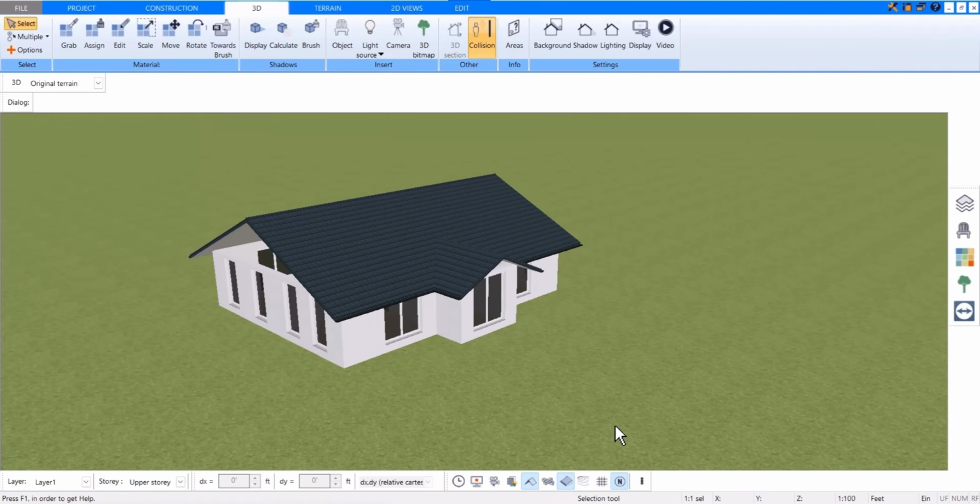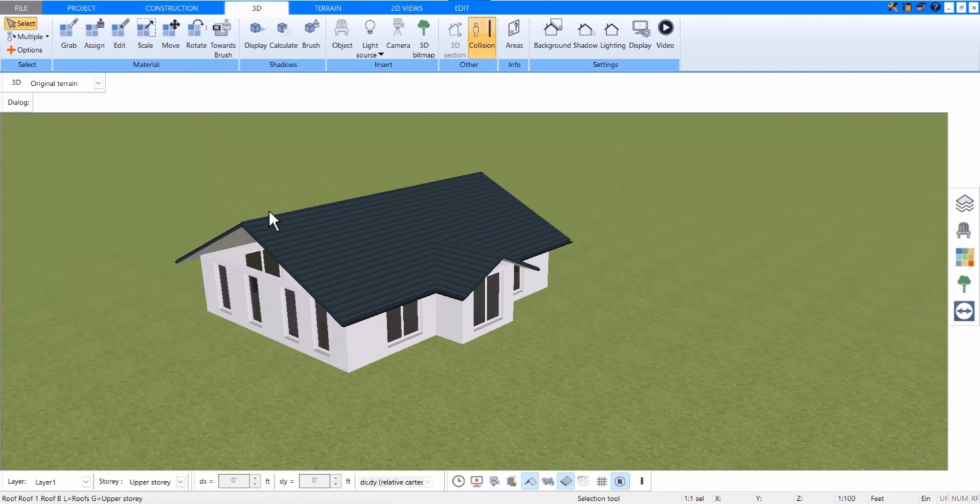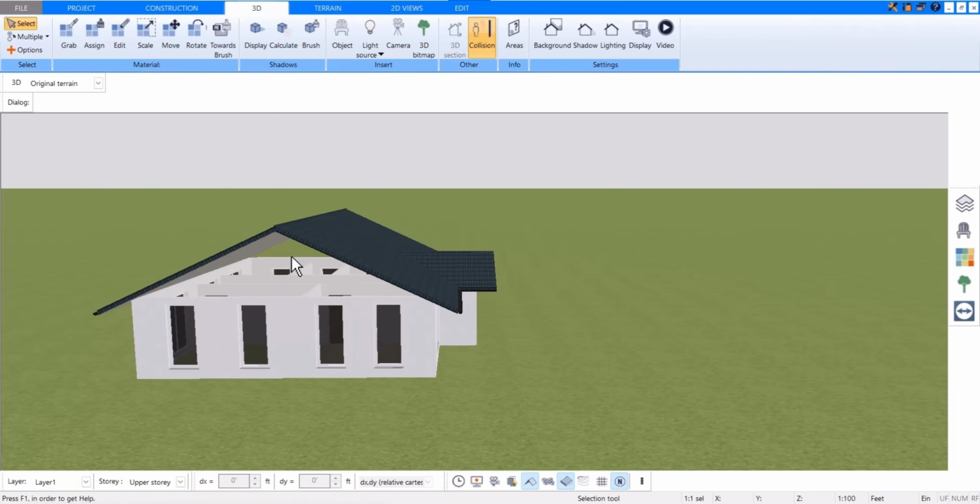For that, I go down to the button labeled Show Wood Framework, and then activate the checkbox under Show. Then the wooden construction of the roof is displayed to me, which can be extremely helpful, especially for more precise planning. Now, in the 3D mode, something else is noticeable. The walls have not yet been trimmed to the roof.